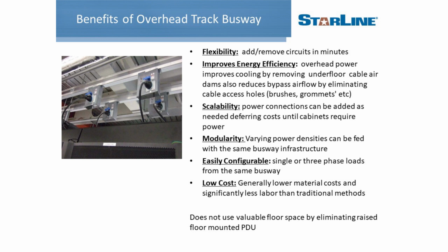That's an issue that we continue to hear about. So being able to add those circuits as quickly as you can, and without de-energizing the busway, is definitely a benefit. Then the energy efficiency, so once again, you're removing all those cables from under the floor.